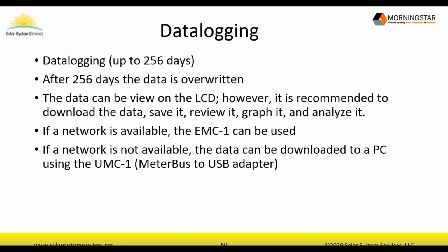So let's jump into the data logging. As I mentioned before, the data logging is for up to 256 days. After that, the data is overwritten. It only keeps the latest 256 days. The data can be viewed on an LCD screen. However, I highly recommend you download it and analyze it. Download it, bring it up in Excel or whatever spreadsheet you use, and analyze it, graph, and look at it that way. And I'm going to show you some examples of that.